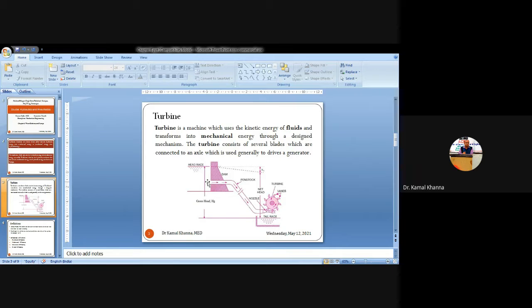So this pipe through which the water is transported from the head race to the nozzle is called the penstock, which is a large diameter pipe through which the water is transported. As we have read in the previous chapter also, here we have installed such a tank so that there will be no chances of water hammering or knocking in between the penstock, and there will be no corrosion or wear and tear of the penstock.